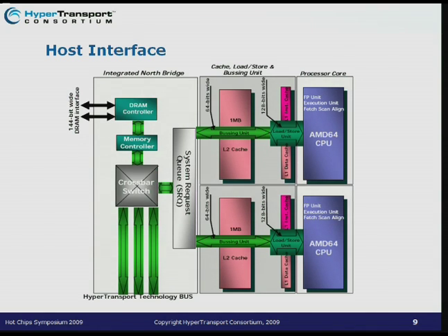They also need some additional routing information so that the particular memory controller with the cache line attached to it, or storing the memory attached to it, is the one that's accessed. So you may think that we are introducing too much complexity because in order to reach a memory controller that's located on chip, we need to build packets. But that's absolutely necessary if we want to fulfill the goal I mentioned before of a unified interface for local and remote memory accesses, because this is the only way we can have this unified way of accessing memory.